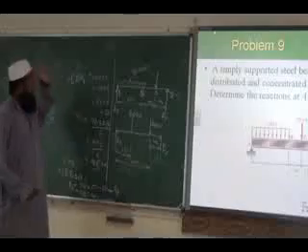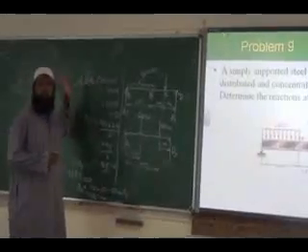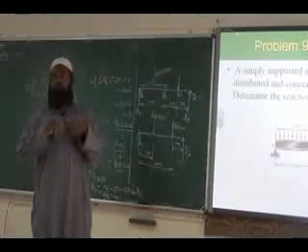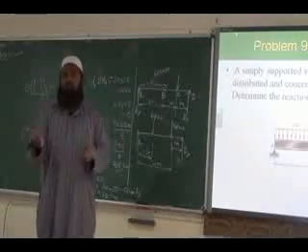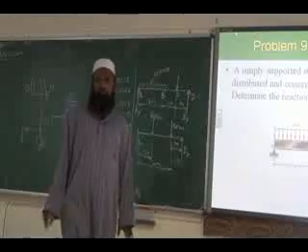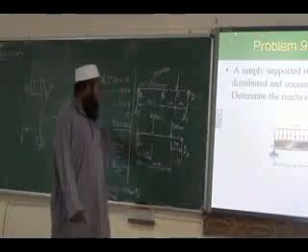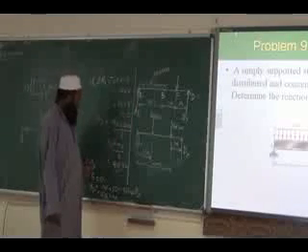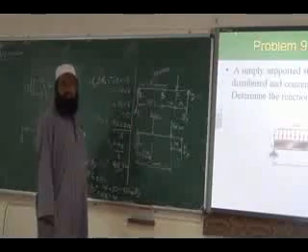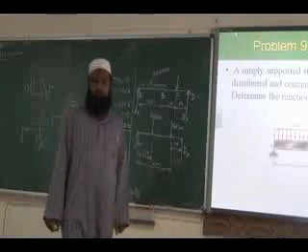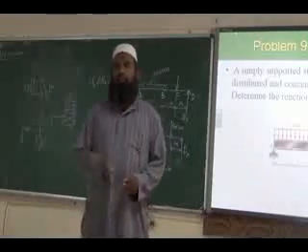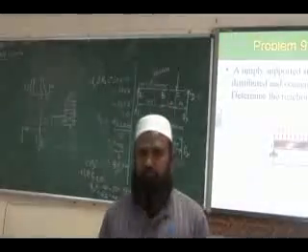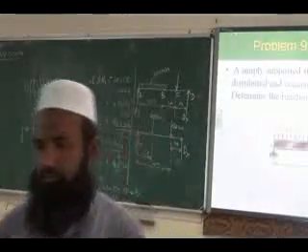Okay. So first, always use the moment equation to get one unknown. Then for getting the second unknown, you can use the moment about the other point, or you can consider the force equation. You can take moment about the other point like sigma Md, moment of all the forces about point D, or you can just consider sigma Fy. Sigma Fy will be easier. You need not multiply it by the moment arm, and the calculation will be simpler.